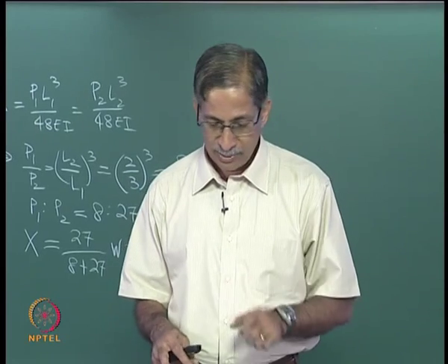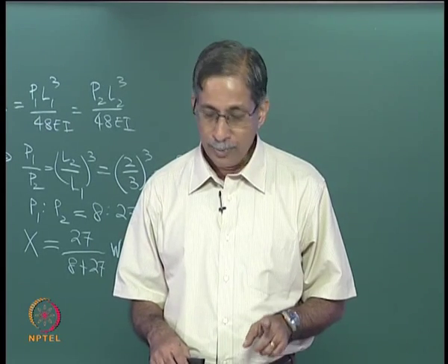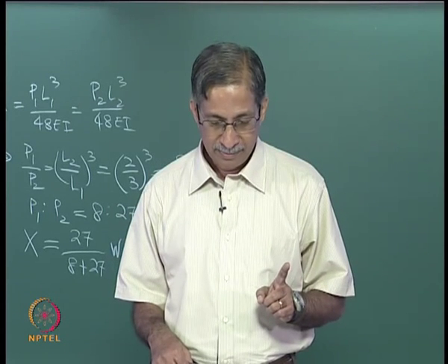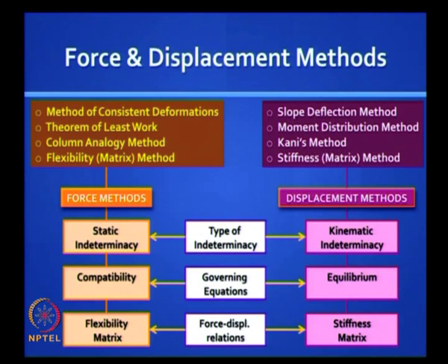All I wish to point out here is we have done theorem of least work and method of consistent deformation and the traditional methods for force methods. If you have the time, you can look up the column analogy method, it is there in the book, which is a very elegant way of solving some problems, especially problems with non-prismatic members. It is a beautiful method.